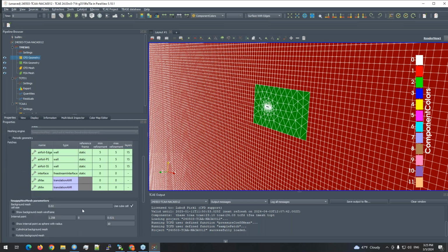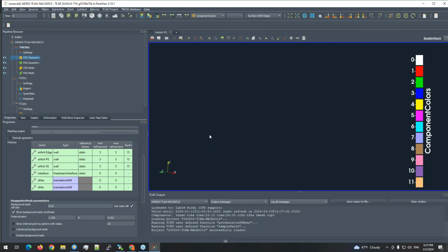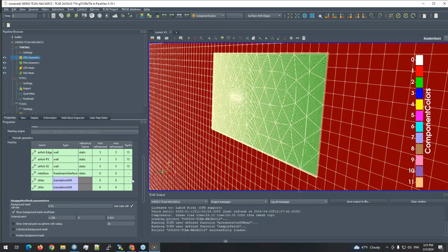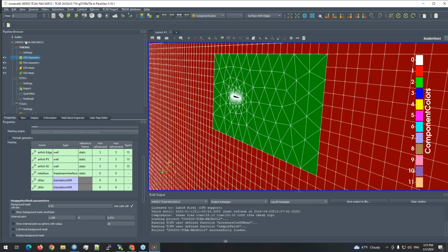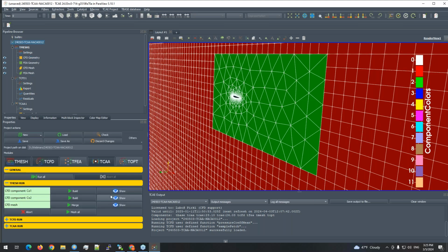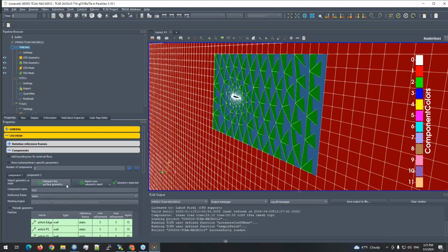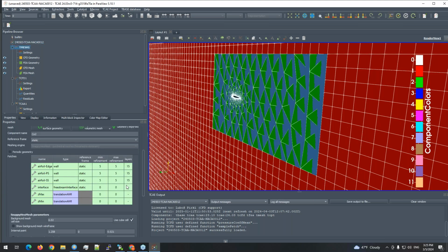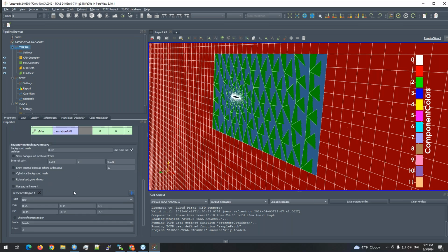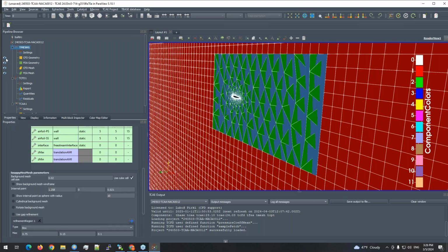It has not been set yet. So that's not a mesh. The mesh is much finer, and we have complete control over it. For example, we can say we will have 15 inflation layers, what the refinement will be, how many levels, etc. So we have all the options over the meshing. What we are seeing here is not the real mesh. That's just the surface that surrounds the volume mesh.